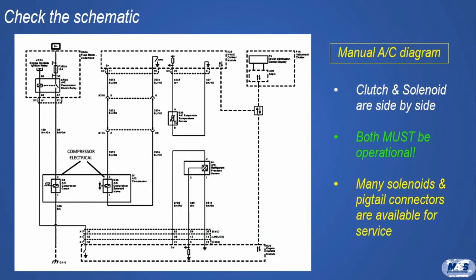A look at the wiring diagram explains it all. In addition to the clutch, the compressor has an electronically controlled solenoid valve, and all the jumper wire does is energize the clutch. With the solenoid not activated, it had defaulted to a minimum displacement. Many technicians have the incorrect impression that if there's a clutch, that's it for compressor control.